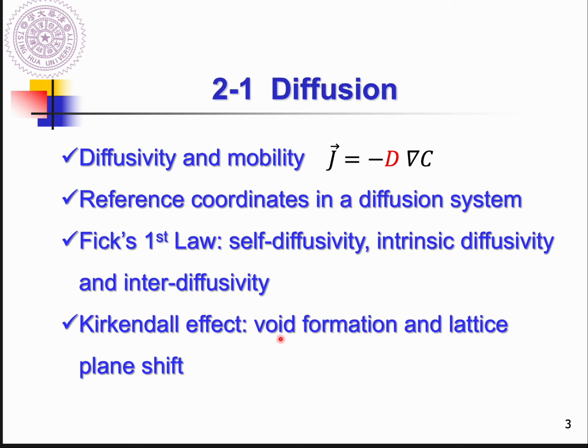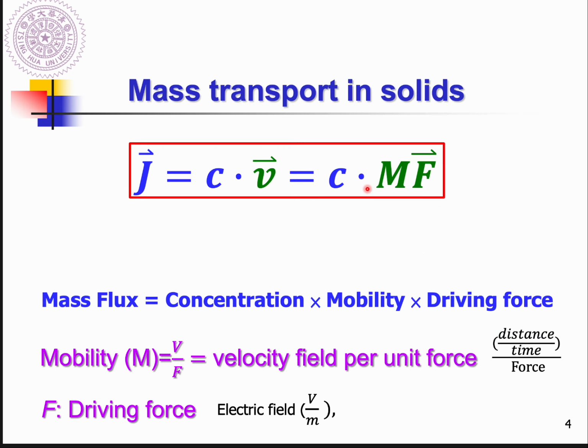And the characteristics of this Kirkendall effect are the void formation and the lattice plane shift. And also, what are the applications of this Kirkendall effect in material synthesis? So let's move to the first one.